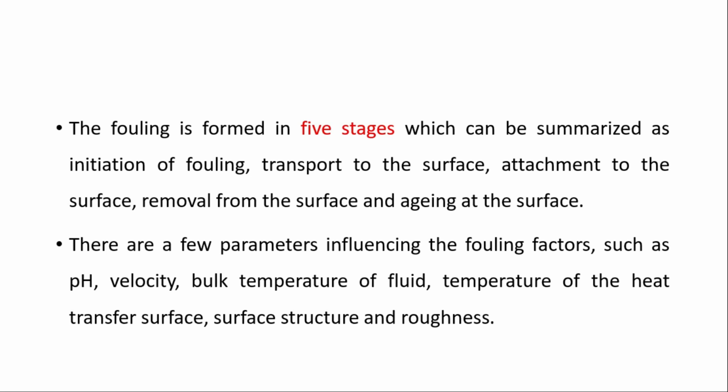There are a few parameters that influence the fouling factors, such as the pH of the fluid, the velocity of the fluid, the bulk temperature of the fluid, the temperature of the heat transfer surface, the surface structure, and ultimately the roughness of the structure, which influence the fouling of the particular heat exchanger.